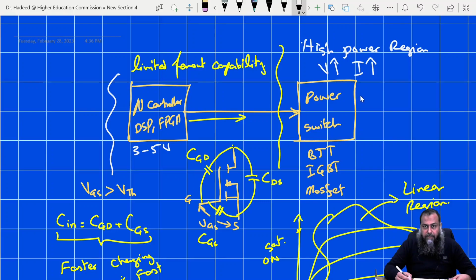And because the power semiconductor switches are used to control the flow of power from one side to another, there is a lot of magnetics involved in the actual circuitry of a converter, and on top of that we have inductive and capacitive behaviors in all real life systems. Therefore, it might happen that if we have, for example, a voltage spike occurring on the power switch side, it may be transferred onto this microcontroller, and therefore it can damage the controller itself. And therefore, the direct connection of this microcontroller is not a solution in a power electronic circuit.